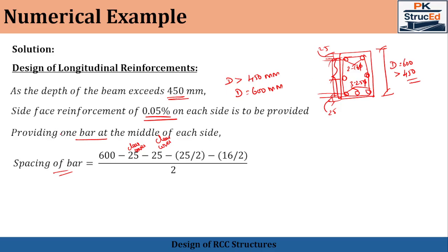And we are going to provide 1 bar at the middle of each side. That is why divided by 2 has been given. So we get that value as 264.75 mm. At this particular location only, at a depth of 264.75 mm from the base, we are going to provide the side face reinforcement.